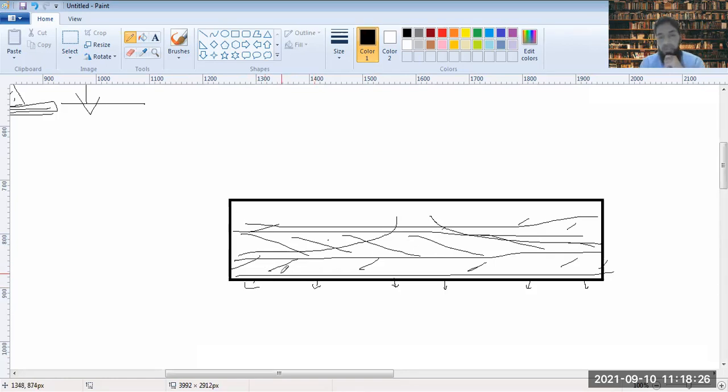But the main issue is it's settling down in layers. So you are actually getting a concrete which is separated into layers, and that will not serve the purpose, because it will create a concrete in beam with layers one above the other, and there could be small horizontal joints between the two layers, which you have casted earlier and which you are casting later on, and you do not want that.